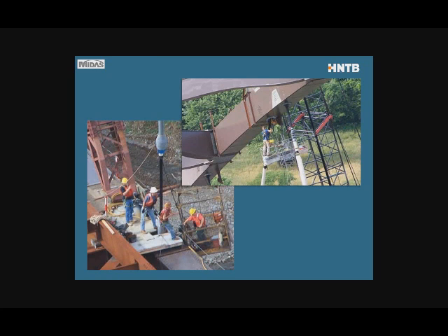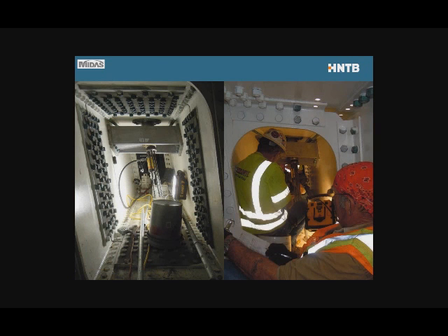The strand is pulled up inside the pipe, and then a worker inserts the strand through the arch rib, through the wedge. Upper wedge is seated, lower strand is stressed. I promised you a picture of a much more constrained site. This is inside the Lake Champlain Bridge, which was only, I think, 4.5 foot deep. You can see the very light stressing equipment that is sufficient for this strand-by-strand installation.